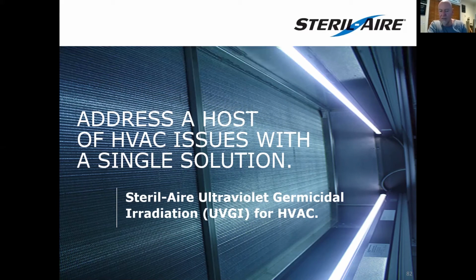He then looked at solutions, and he started testing UVC in a laboratory. And it worked successfully at inactivating the microbes. He then applied it to air conditioning systems, but to his embarrassment, it didn't work. What he found was when you introduce conventional UVC lights into cold and moving air, their output drops. The reason their output drops is because they can't maintain the photon production. They can't maintain the gas temperatures. So the lamps cool and the output drops significantly.